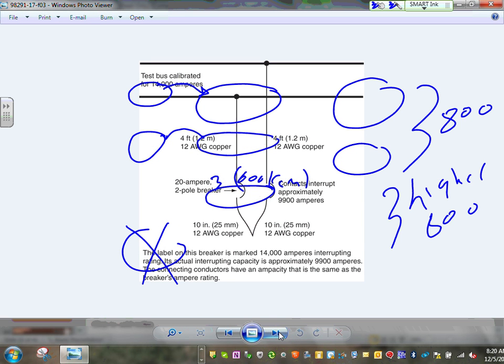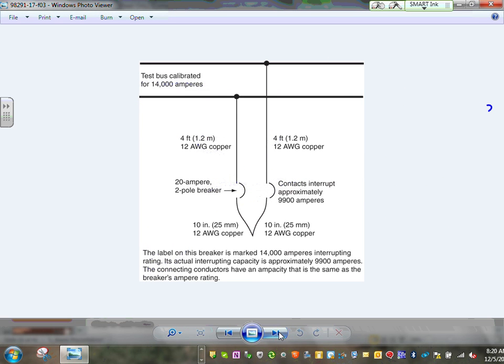Short circuit ratings. When it comes to the short circuit ratings and interrupting ratings for motors, for example, here's number 12 sitting here. Can you guys see they take phase A and phase B together? That's your short circuit, and that's how they come up with the interrupting rating for circuit breakers. So if the circuit breaker can handle that one, we're good to go.